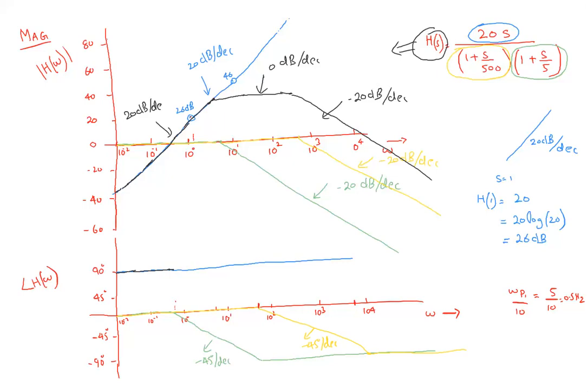So जैसे 50 radians per second पे आएंगे, we'll reach the point which is ये. क्यों इस तरह हमारे पास आ रहे हैं? Why we are going down like this thing? Because हमारे पास initially phase है 90. That phase is now going to be nullified with the help of first pole, which occurred, and with a -45 degree per decade. So till 50 hertz we go like this.